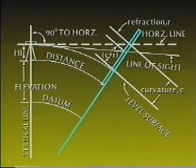As can be seen in the illustration, the greater the length of the sighting, the more the level line deviates from the horizontal line. The more the two lines depart from one another, the greater the curvature correction will be.